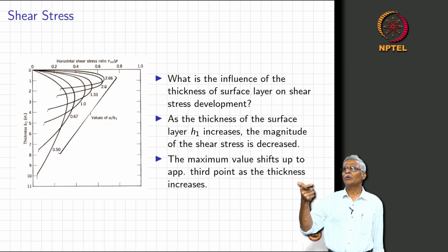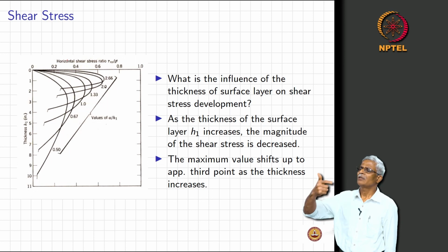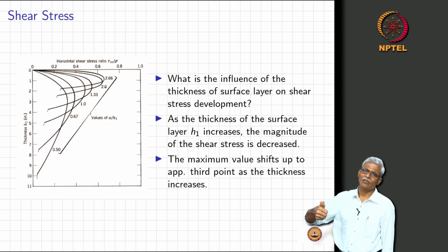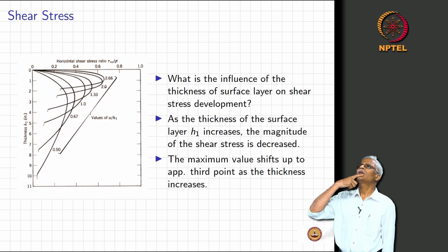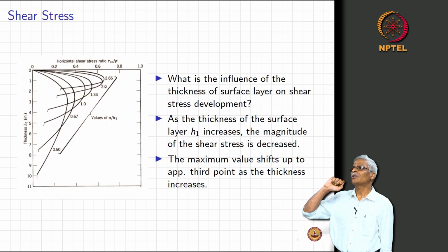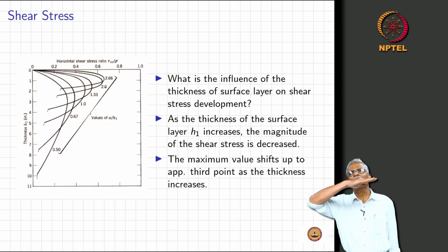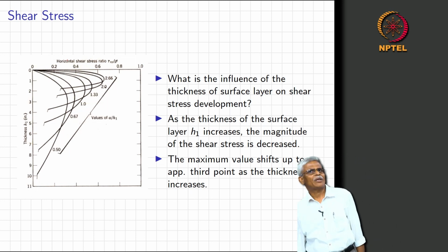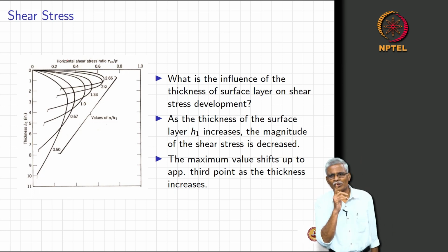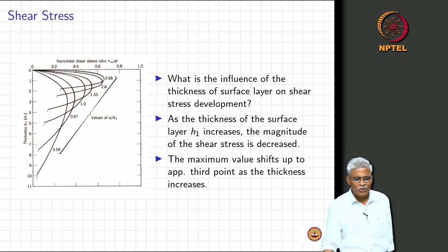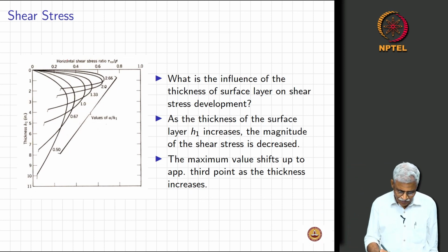Now, the second thing, what about the deflection, modulus and layer thickness? Increase the modulus, there is a greater reduction in the deflection. But when we come to the shear stress, you realize that if you increase the modulus value considerably, there is going to be considerable shear stress, and the maximum shear stress is going to be somewhere at mid depth. Okay. So, now you are thinking, should I increase the modulus or increase the thickness? So, let us try to see what is the role of the thickness as far as the shear stress is concerned.